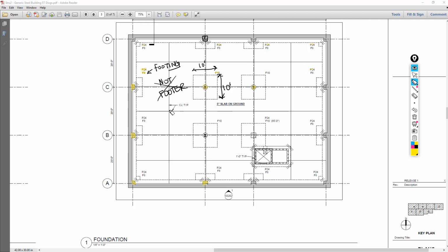Also on this plan, you can see that there are some lines, vertical and horizontal, and a tag here noted CJ, and CJ stands for control joint. So as we will discuss in just a minute, concrete expands and contracts, and so we need to provide some areas where it can move, otherwise we will get cracking through the floor slab.